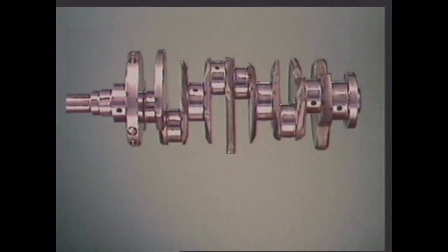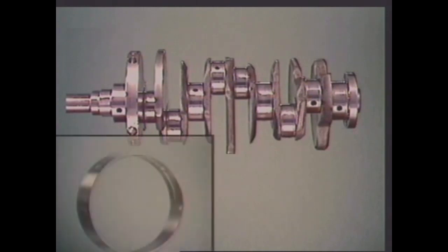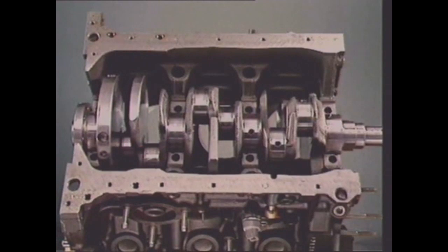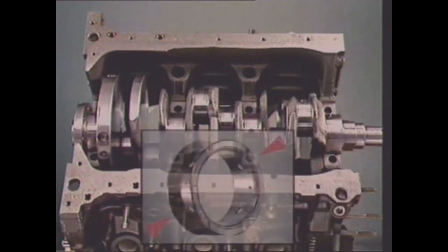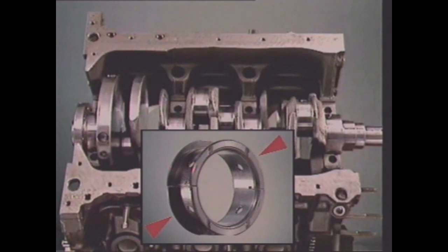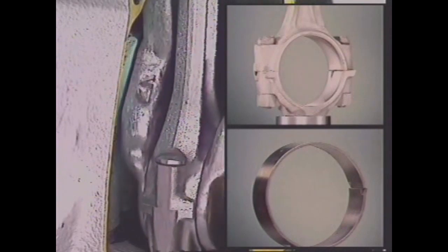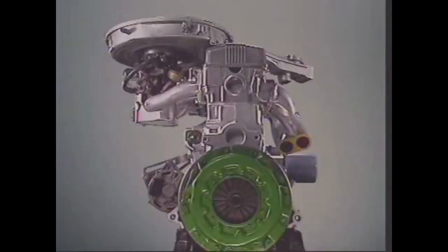Different bearings do different jobs. These bearings support the crankshaft in place but let it turn freely. The crankshaft also needs to be located to stop lateral movement. This is done by using flanges. Between the connecting rod and the crankshaft are connecting rod bearings. They protect the spinning crankshaft at points also called journals.